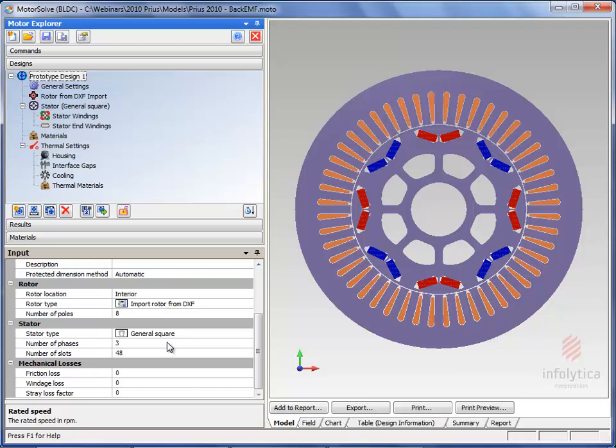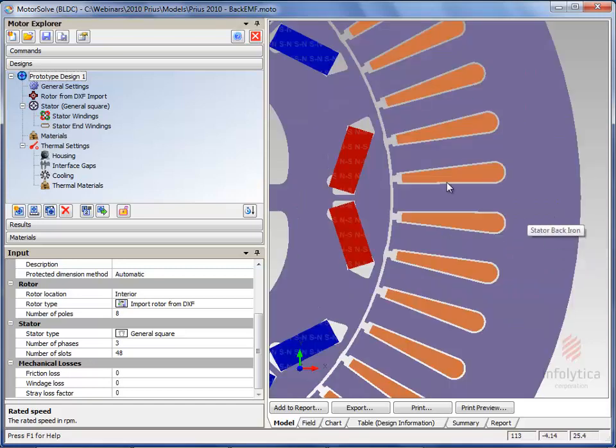You can see here that we've got a very complicated rotor structure with hollow core and spokes for the interior of the rotor. We've got very unique features centered around the magnets, as well as a dimple in the outer perimeter of the core.